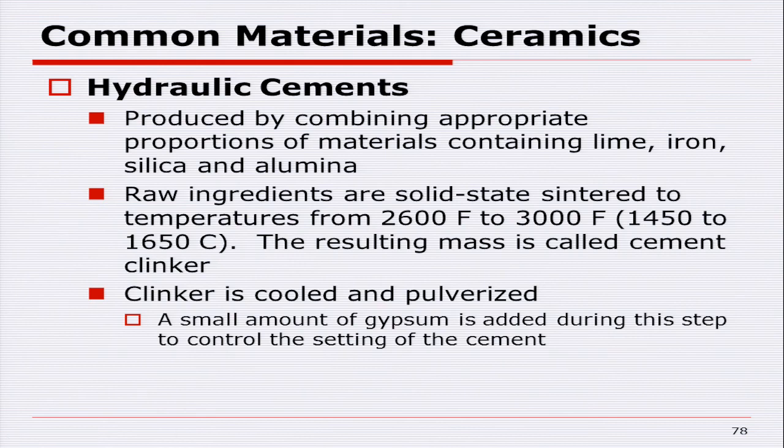and they will sinter, and then you're going to grind it and pulverize it, and typically add gypsum to it to stabilize it so it doesn't set up in the bag. Basically what you're doing during this whole process is you're taking away the water, and it wants its water back, and you give it its water back when you're making concrete.